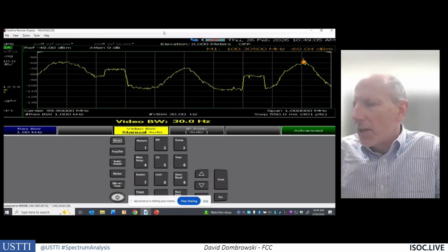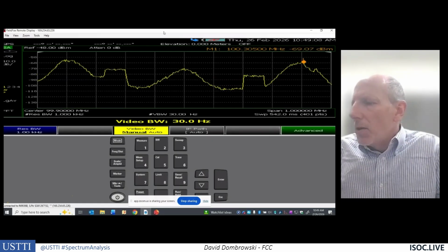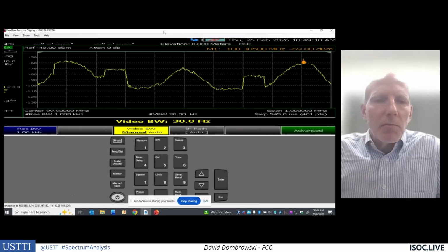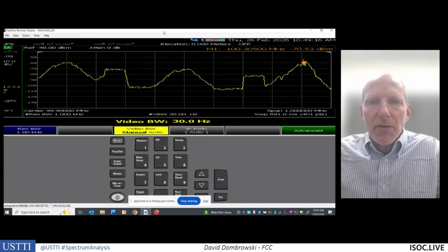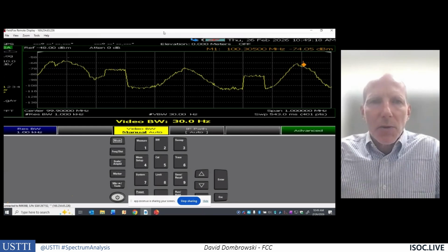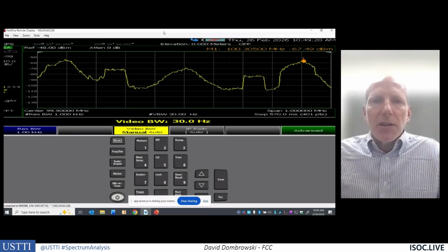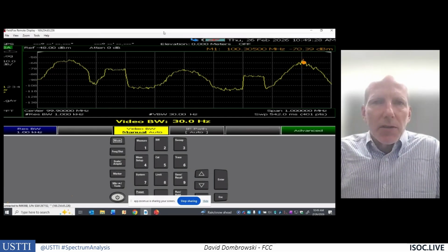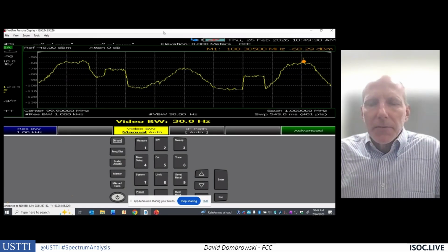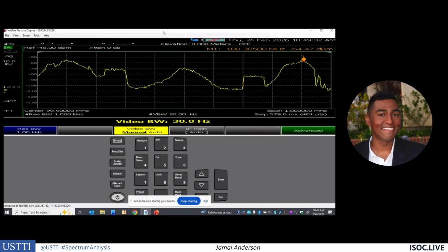Okay, for measuring modulation, we typically don't do a lot of modulation measurements, but we typically do our measurements with a 150 kilohertz span, because that's where you're getting most of the energy of the signal. So 150 kilohertz to 200 kilohertz would be appropriate for the analog signal. Okay. Next question. Would it be difficult to read an uplink signal to a nearby site by adjusting the parameters?